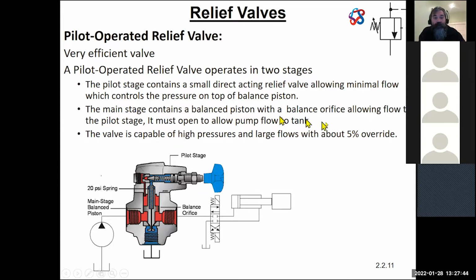So we've got here a pilot stage that contains a small direct acting relief valve allowing minimal flow, which controls the pressure on the top of the balance piston.